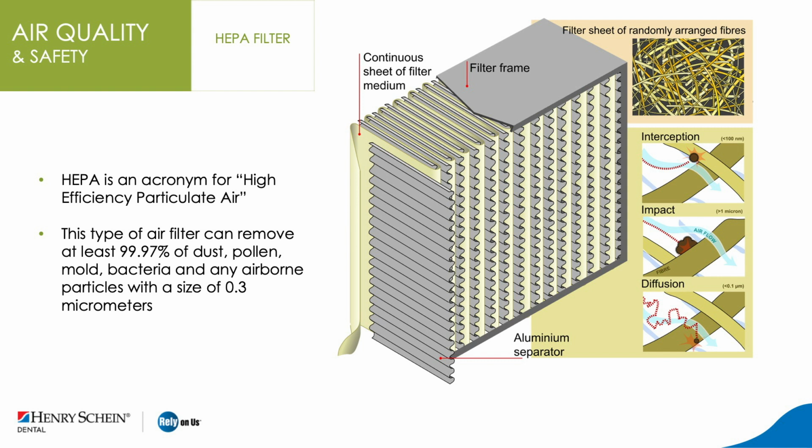And if you were running an accounting office, something like that, that would be just fine. But a dental office has much more physical activity in it. And so what we need is more air conditioning, sometimes even in the wintertime, even in northern environments. And so we're going to have 1 ton of AC for every 275 square feet of office space.